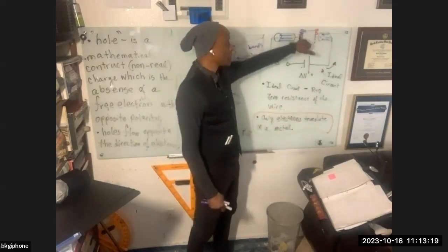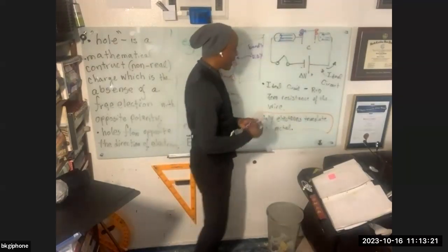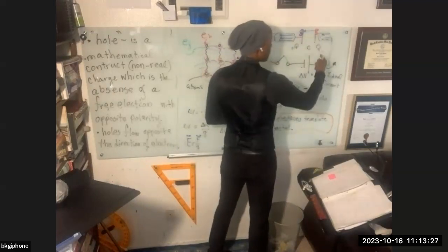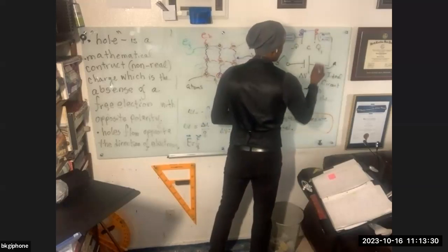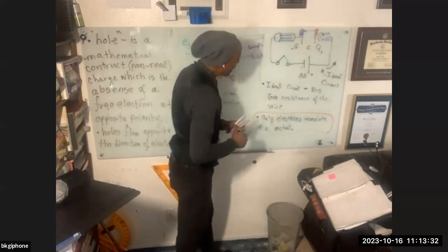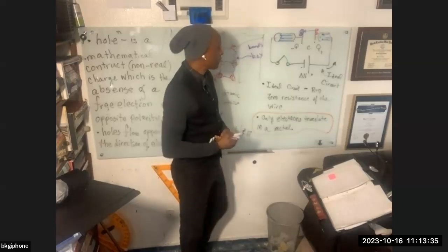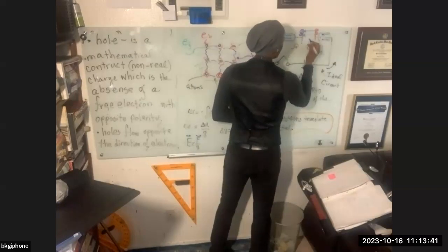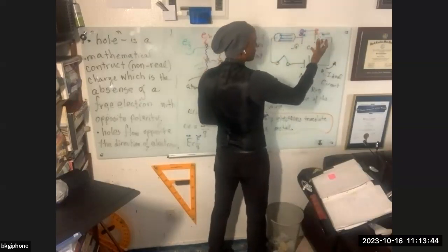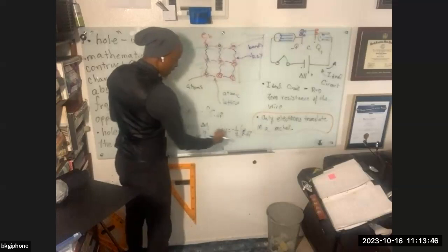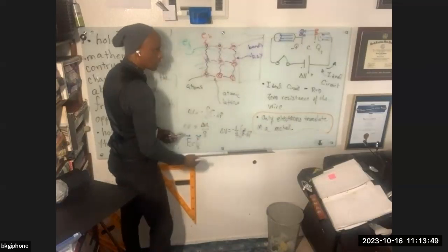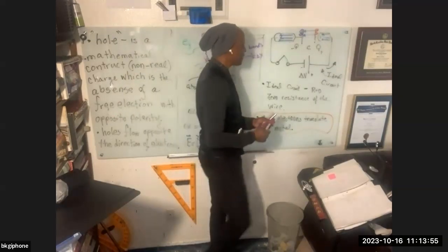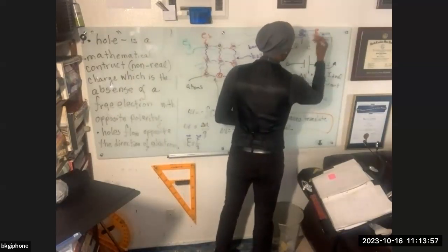The one is the charge accumulating, right? We've now defined a positive plate and a negative plate, Q positive, Q negative. And so we've got charge building up. We've got an electric field building up in between the capacitor plates, E. And because of that, we have a voltage, right? They're all related through the relationships I've given. And that just keeps happening until the capacitor is fully charged.